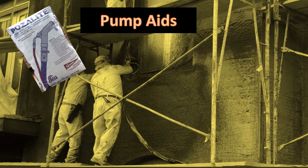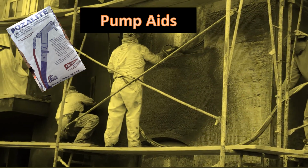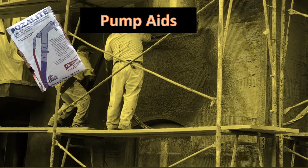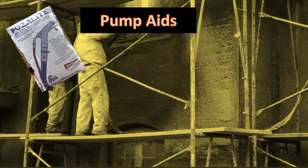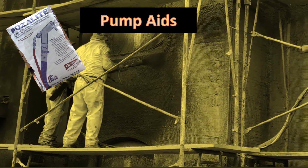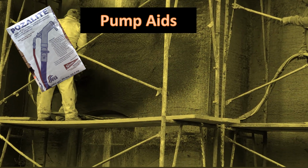Pumping aids. As noted before, pumping cement can require a wetter mix to allow for that slippage in the hose. Another method to gain that lubricating effect is to use a pump aid. These can make plaster flow easier through the hose. You should only use products recommended for plaster pumps.